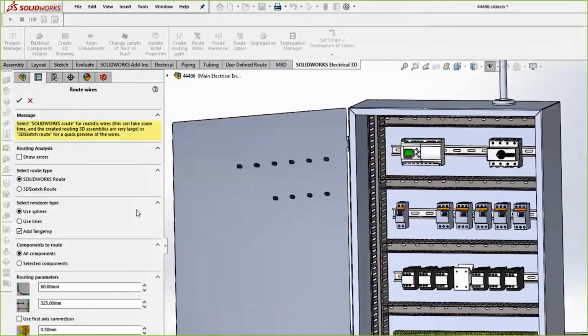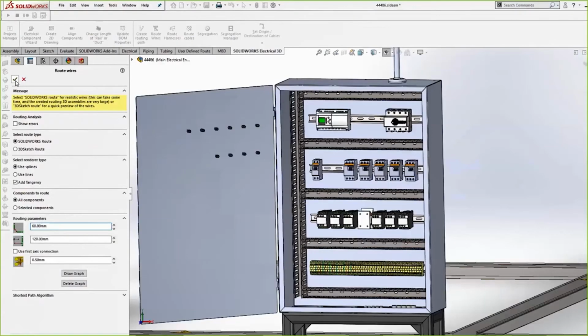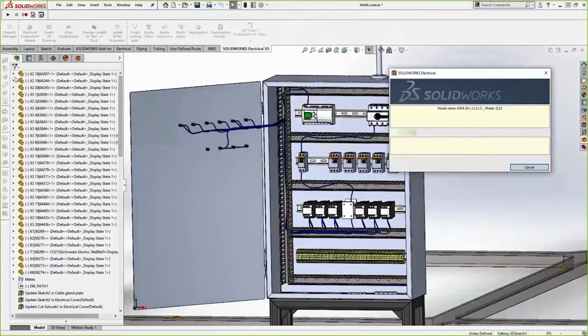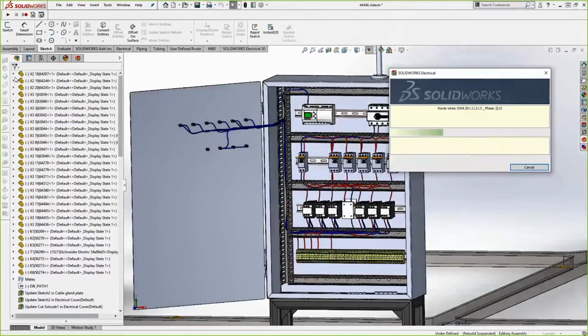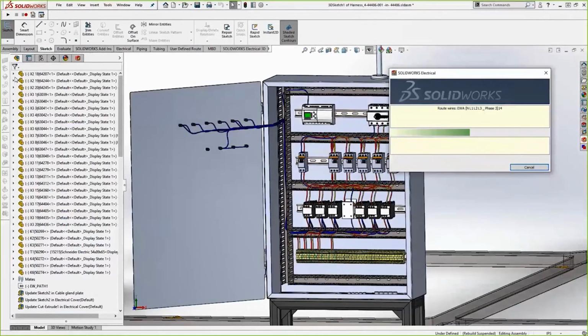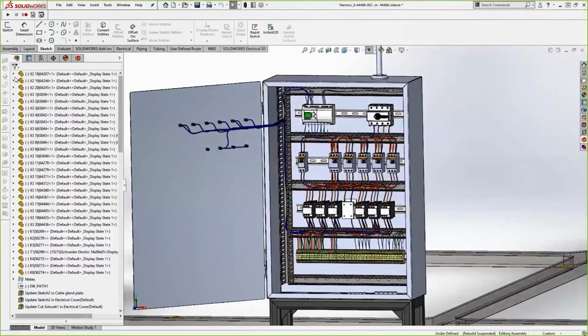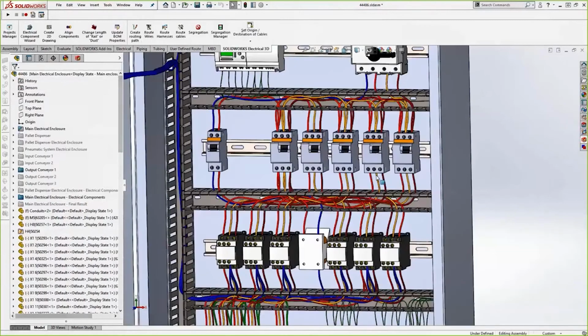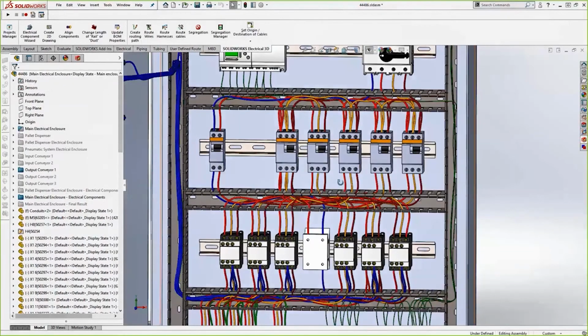So the nice thing here is I've got a schematic. I know what everything's connected to. I've got all my components, and they have routing points assigned. So what that means is I can actually auto-route my panel. And these routes, it's actually taking that wire information from the wire styles in the schematic. It's looking at the color, the diameter, and violations of bend radius. And it's actually auto-routing the panel just from a sketch behind the scenes. So I can quickly block out a sketch, and it'll spline along that sketch. You can see we get a really nice realistic length and view of our panel.